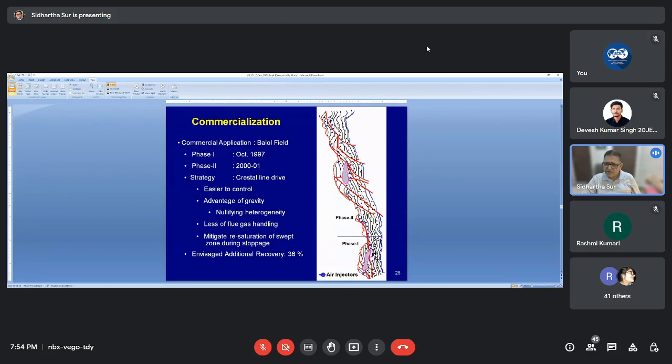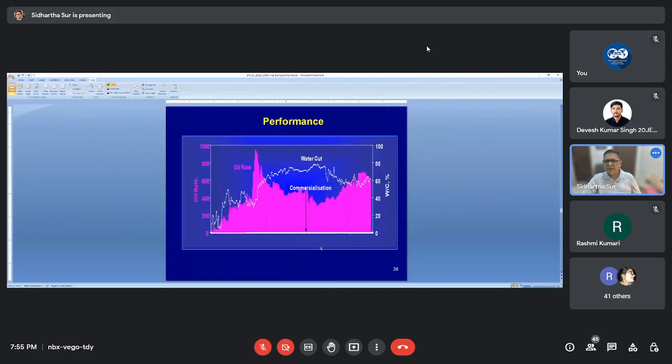Here there is a long distance displacement going on because there is significant mobility of oil, and average recovery factor from here to here is 40%. Significant recovery has taken place. And here short distance displacement is in vogue with a horizontal well and injector spaced close by. So enhancement of recovery, enhancement of production, reduction of aquifer, strength in arresting the aquifer encroachment, all points to the strength of this process.